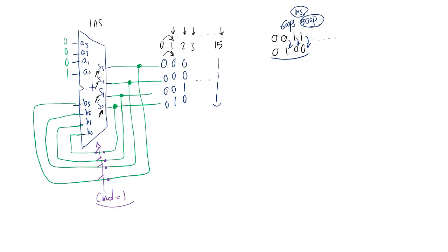And then you can imagine that this command has to be 1 only for a very small amount of time. I'm talking about picoseconds or something like that, right? Because if it's on for, I don't know, a few hundreds of nanoseconds, then a bunch of outputs are going to pass through. It's not going to be 1 output. It shouldn't be on for more than a moment.